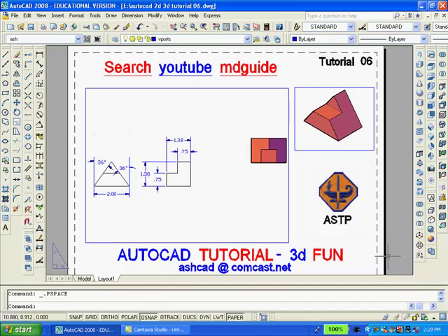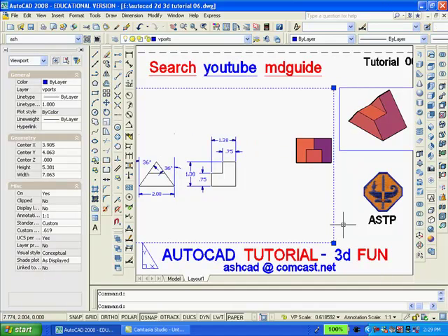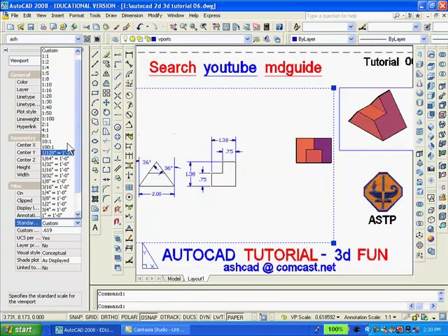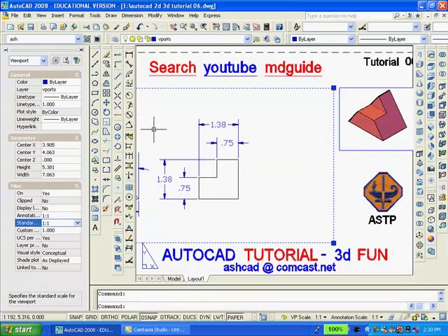You set the scale of the large viewport by clicking the Properties button. Then the standard scale is found under Miscellaneous. To repeat, you select the large window, then go to the Properties button, then you'll go to Miscellaneous. You'll find a standard scale here. In this case, I'm going to set the scale to 1:1.